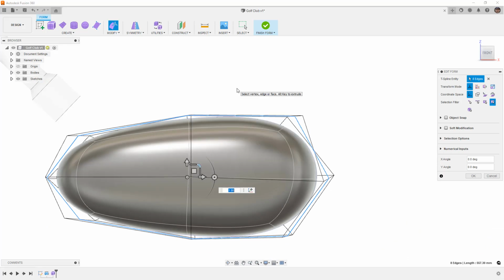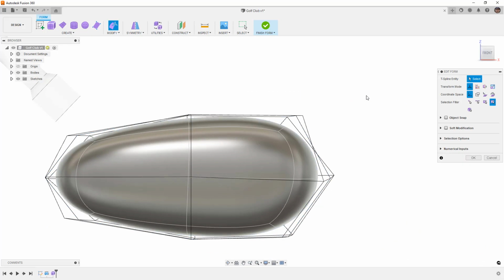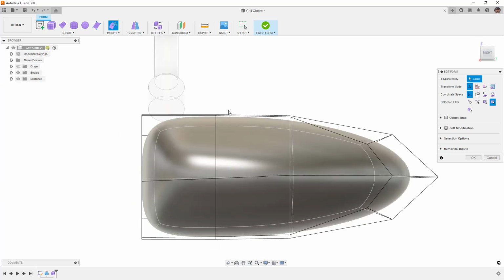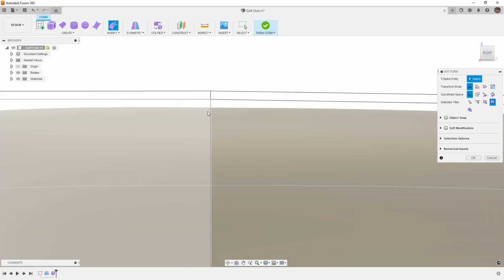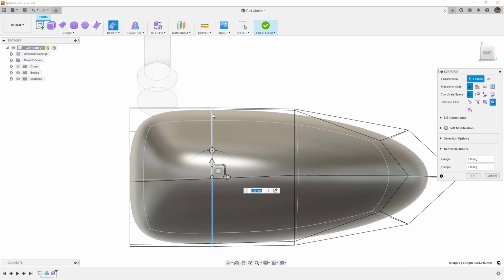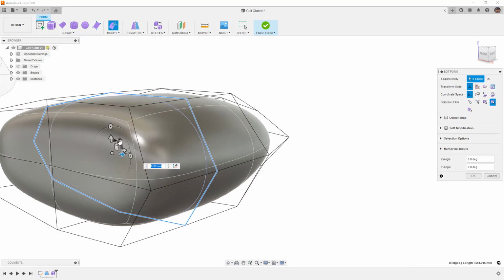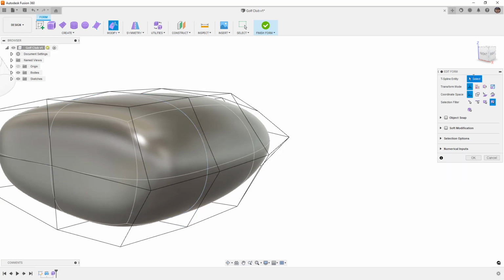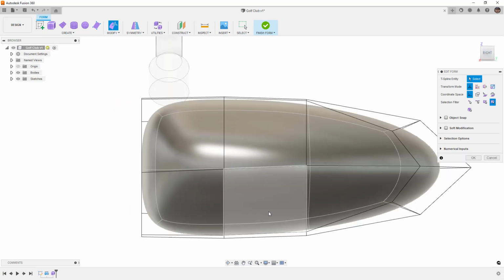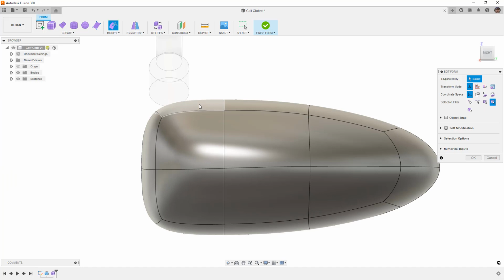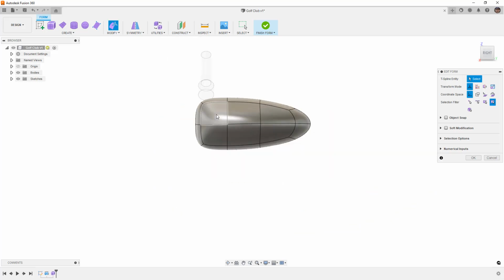So again, I'm going to take this and I'll do 1.01. Just going to give it a little bit of a height increase. It might not be enough, but it does take that out just a little bit. Let's try to scale it up just a little bit more. I'll go 1.02, something a little bit more drastic. And then if we take a look at this in smooth display, so basically what we're doing is we're trying to get rid of the bump that happens in between there.